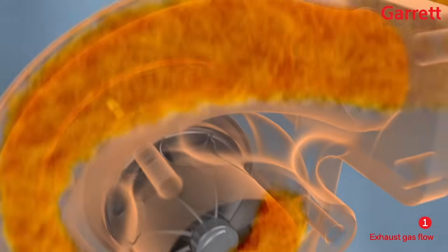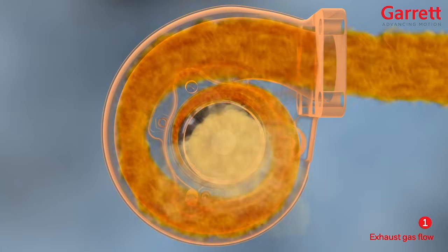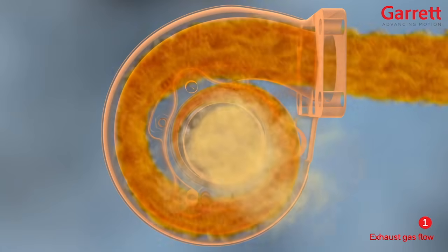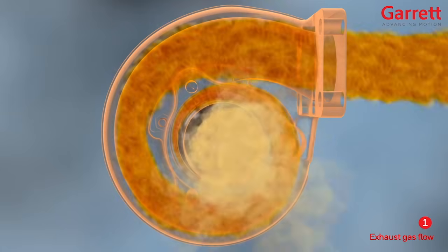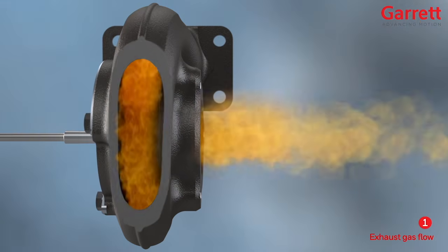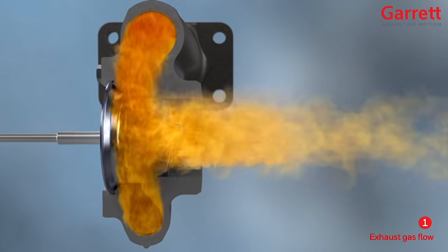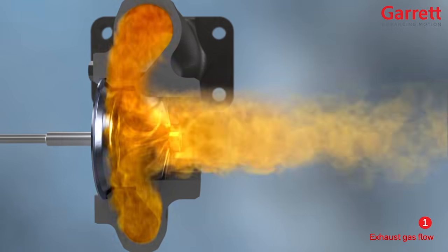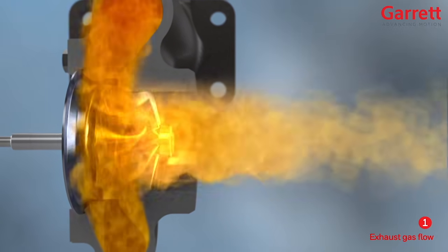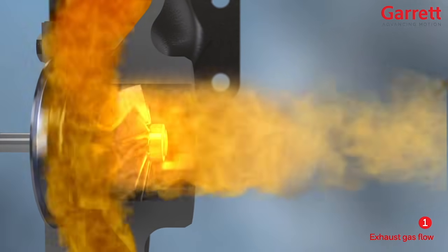After that, the gas passes into the volute, which is shaped like a snail shell with a reducing section, where it is again accelerated to higher velocity. Finally, the gas passes through another nozzle area, around the turbine wheel inlet or inducer blades. Now the gas is traveling at its maximum velocity, and as the gas enters the turbine wheel and passes between all the turbine blades, it is expanding and releasing energy and causes the turbine wheel to spin at high speed.